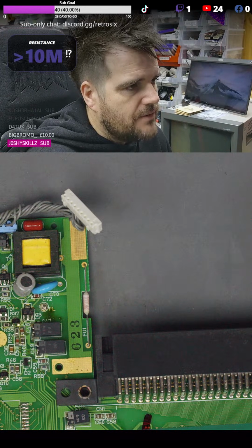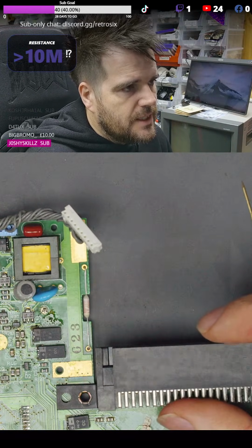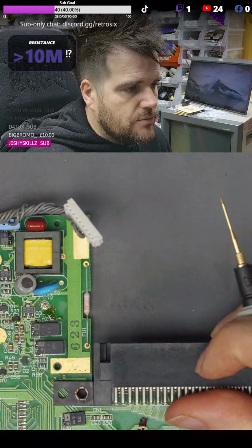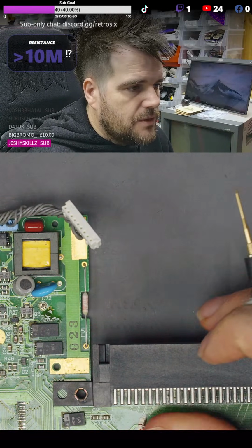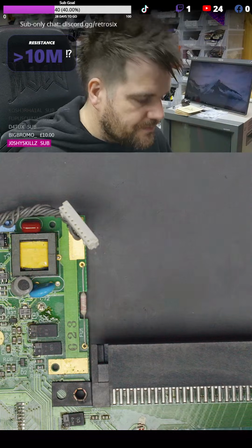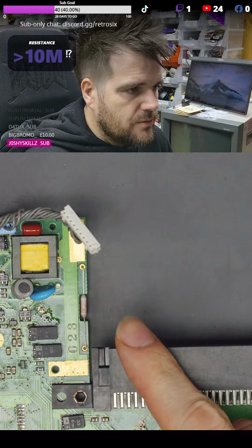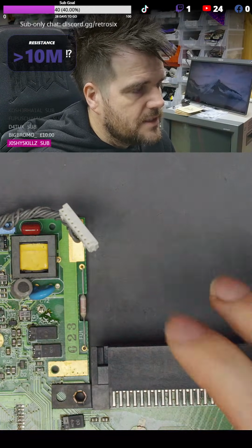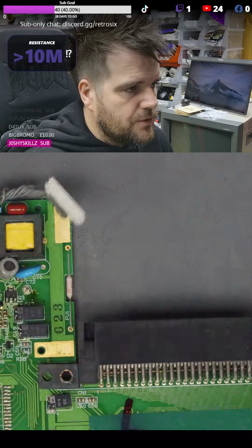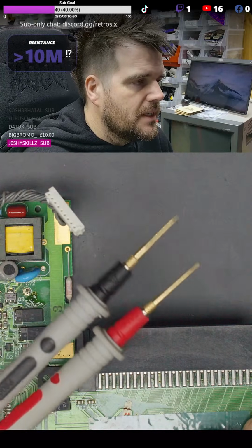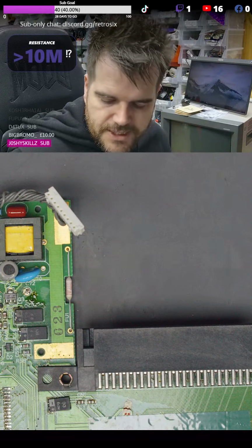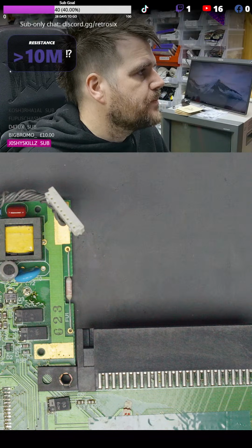Because if this is getting 5 volts, you take 5, divide it by 95 ohms, and that will get you the current that this is going to pull. That's quite a bit of current to sit on a board that shouldn't have a fault. So your first hint that there's a problem is your multimeter. That's one way of detecting shorts, through a multimeter.